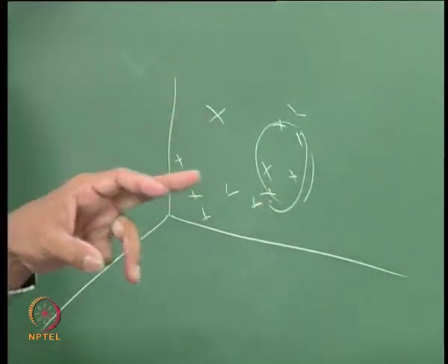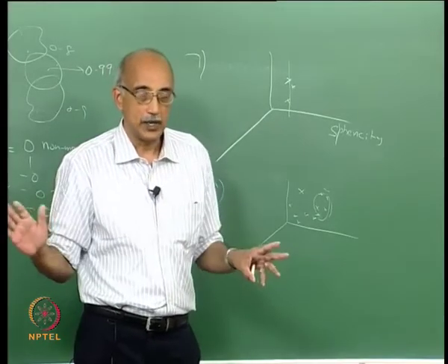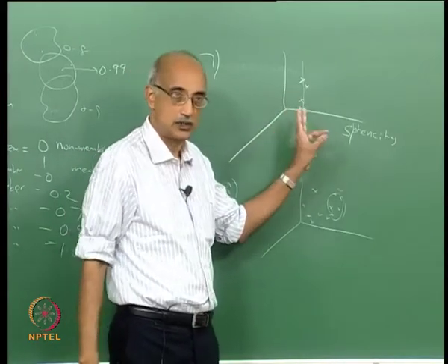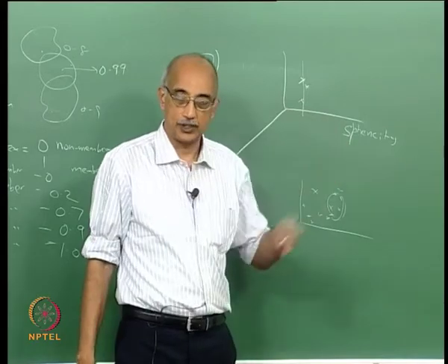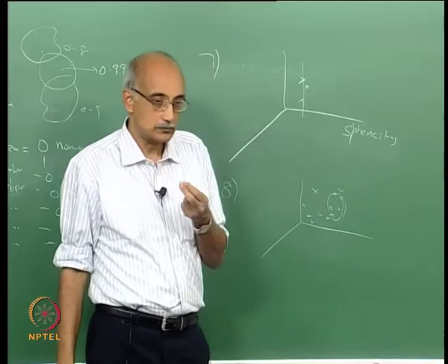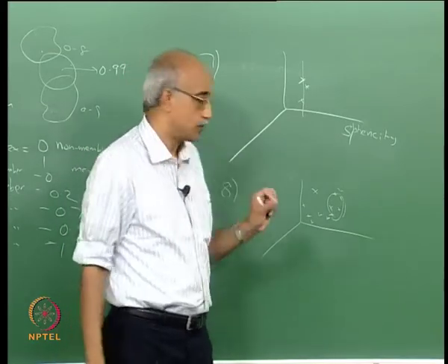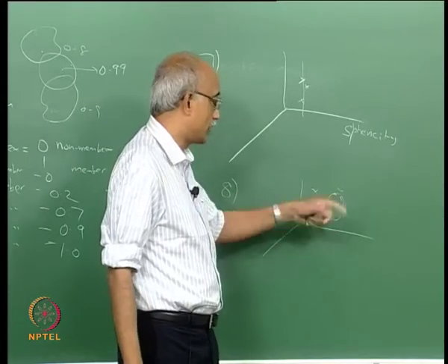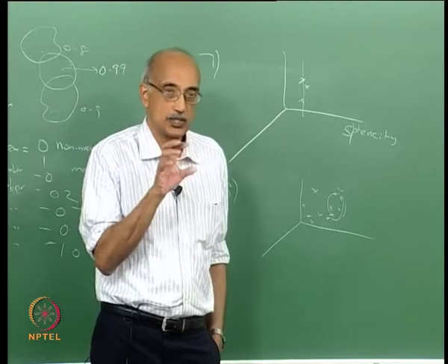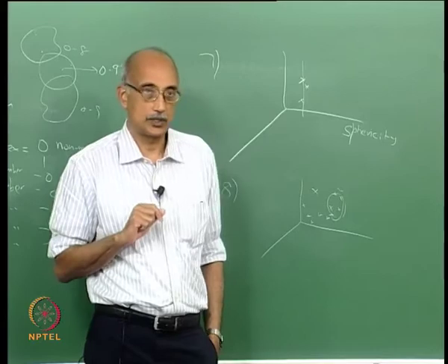The clustering approach works when you have more than one property that is relevant, but at the same time you do not want to do this in a purely empirical, mathematical manner. You still want to carry over certain aspects of the common property approach, but in this case you identify the minimum number of relevant shape characteristics, and find out of all the shapes that you are considering which ones have the closest clustering of these properties to the particle that you are trying to analyze.